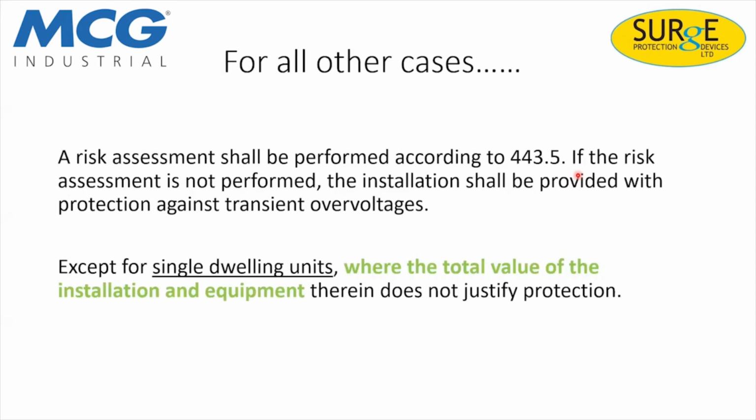For all of the cases, a risk assessment shall be performed according to 443.5, which I'm going to go through in a moment. If the risk assessment is not performed, the installation shall be provided with protection against transient overvoltages, except for single dwelling units, so our domestic installations, where the total value of the installation equipment does not justify protection. So where the total value of the installation equipment. So that's what we've got to consider.